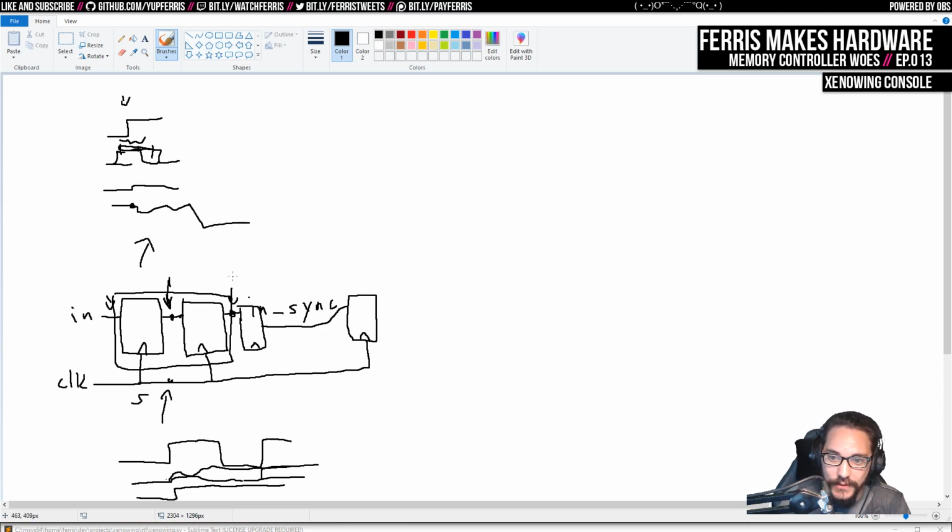And then there's something called mean time between failures, MTBF, and there are a lot of tools that will detect, for example, the Vivado or Quartus tools will detect that you have a synchronizer chain. This is an obvious pattern where you have 2 registers where one's fed into the other. They're both on the same clock, the input is probably a false path that we don't have timing information for, and the output is synchronized to the clock. That's a very easy pattern to recognize, and you can calculate, based on your clock rate and how this is hooked up on the actual device, the mean time between failures, and it's usually a really long time.